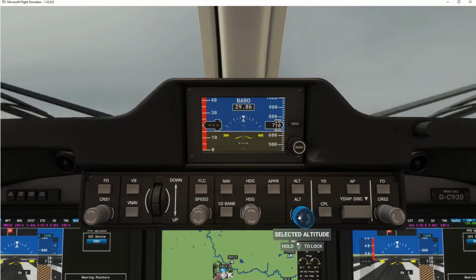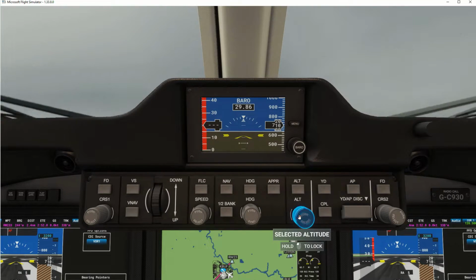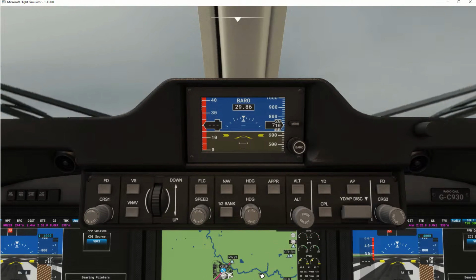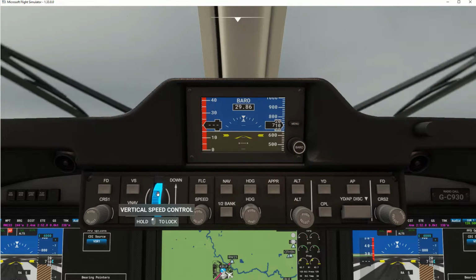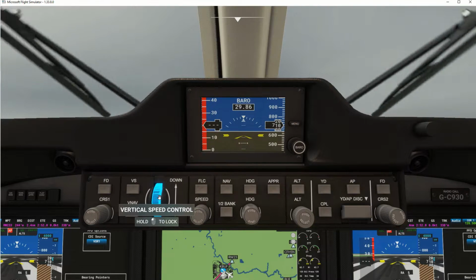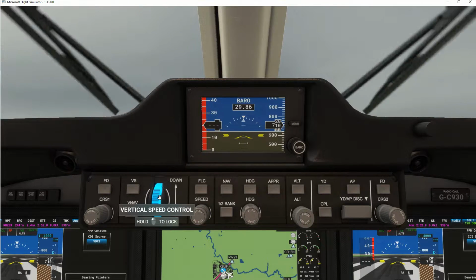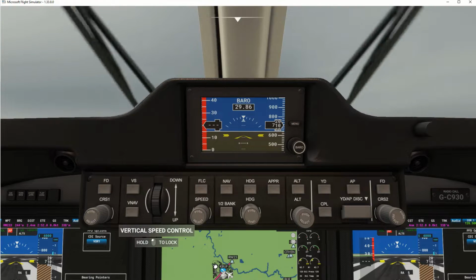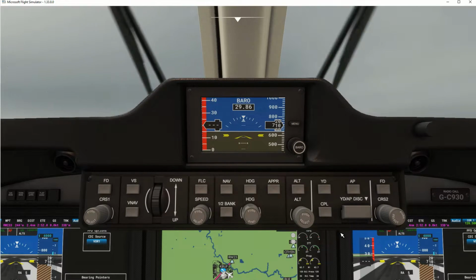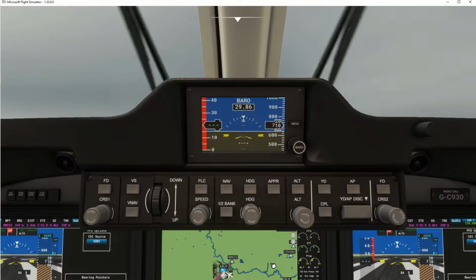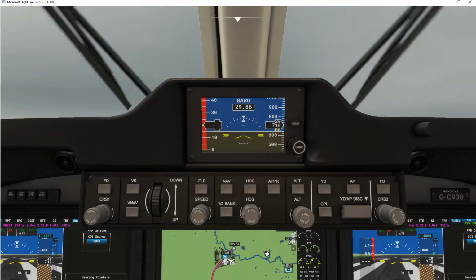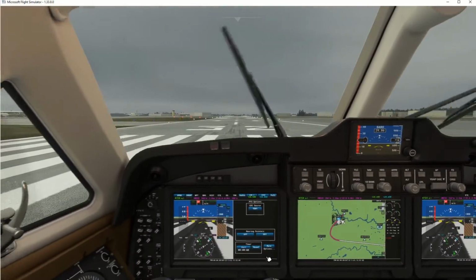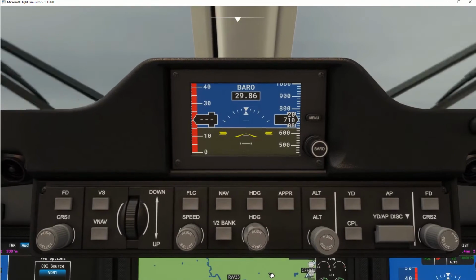So there's an auxiliary screen that has additional information. There's your automatic flight control right here. So we'll be using these buttons here to set the autopilot, flight director, yaw damper, nav. And right now I'm setting the vertical speed ahead of time, to climb. So I went to the vertical speed button. Also have to set the altitude. So I set the altitude to 4,000 for the flight plan.